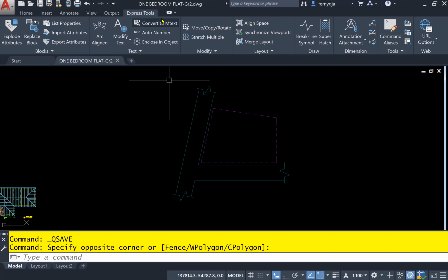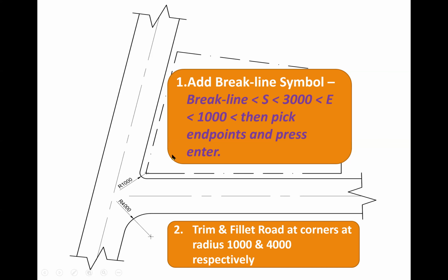Yes, sir. All right. To change layer again, because we need the road center line, which looks like this. So we're gonna offset half the distance, which is 3,000 to the center, 3,000 from here. So for a longer line you would offset 3,000 into the current layer. So set your C road center line layer correct.